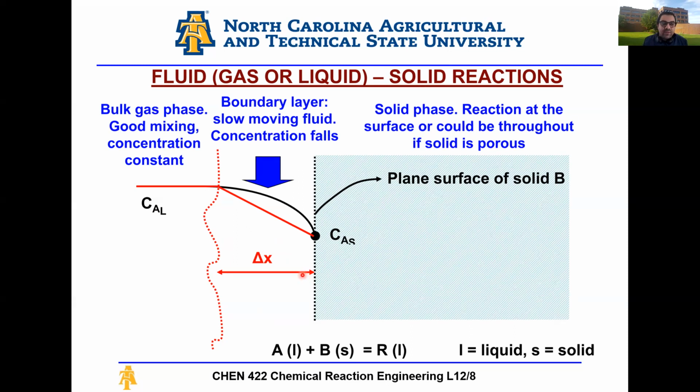or controlling these elements. If you have a gas liquid flow, maybe making the bubble size much smaller so that your surface area to volume ratio is much higher. If you're running in a CSTR, you have maybe an impeller which mixes the system very well, and you don't have a lot of dead zones, as we talked about last time. And these will help to reduce the mass transfer resistances in your process.